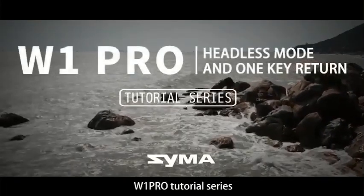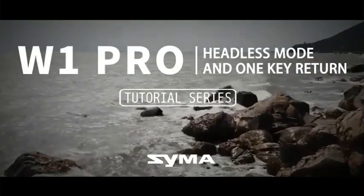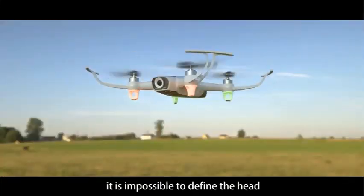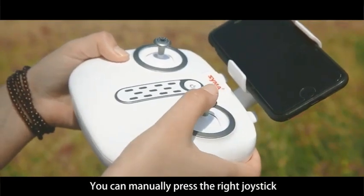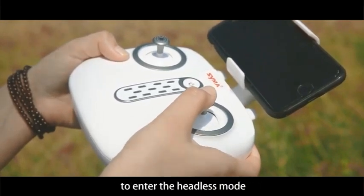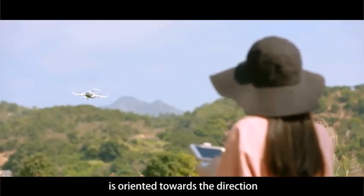W1 Pro Tutorial Series: Headless Mode and One Key Return. When the aircraft is flying far away or the line of sight is blocked, it is possible to define the head orientation of the aircraft. You can manually press the right joystick on the remote for 2 seconds and wait for the remote control to make a beep-beep sound to enter the headless mode. Under the headless mode, the aircraft is oriented towards the direction of the remote control.